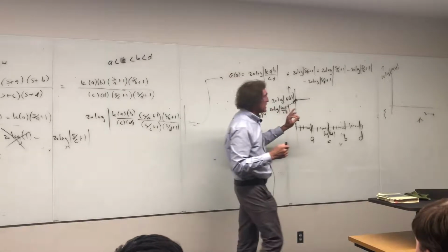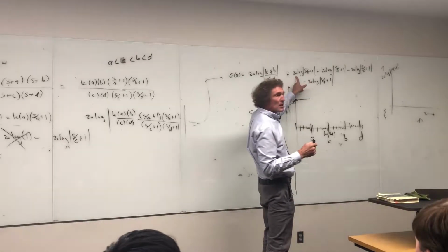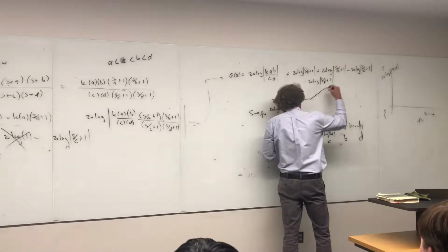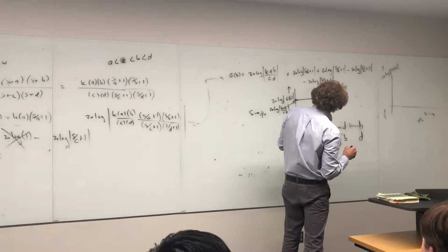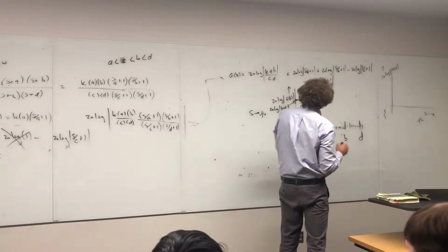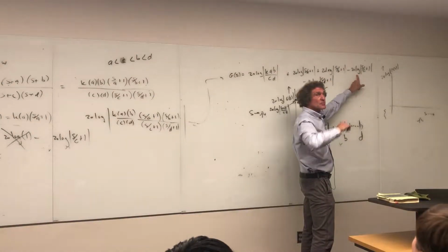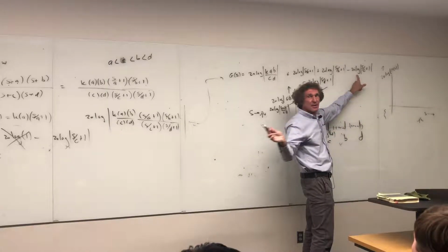Now, when you do this here, I say that starts, and you see how it's a positive 20. So it starts going up at a rate of 20 dB per decade, all right, until it hits C. I said C was the next one. When it hits C, then it starts going down. Well, it was already going up. It means it gets canceled. It just stays at the value it's at. Does everybody hear me on this one?